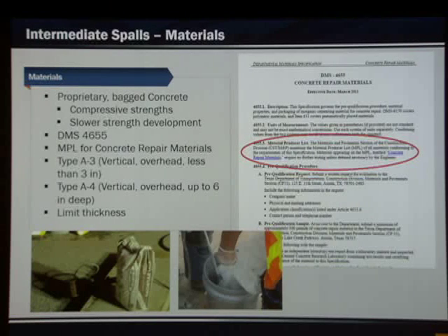So that brings us to intermediate spalls. For these type of repairs, the recommendation is for proprietary bagged concrete. And now I'm going to tell you something that kind of blew my mind. And that is that compressive strengths that are higher do not necessarily equate to a better patch.